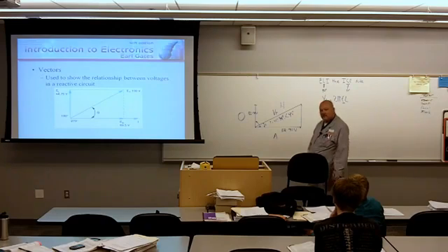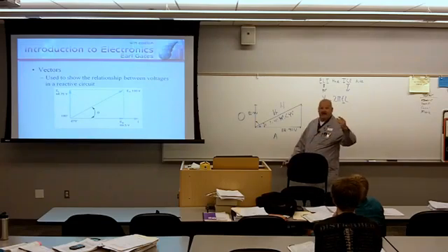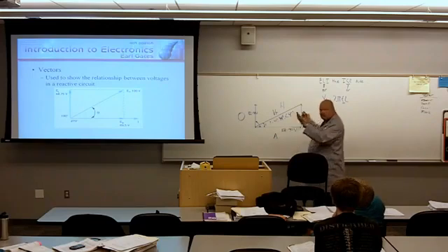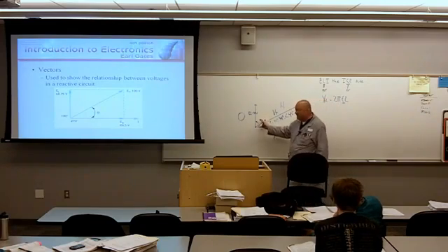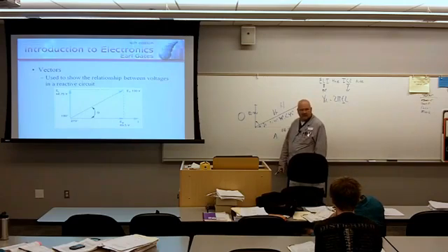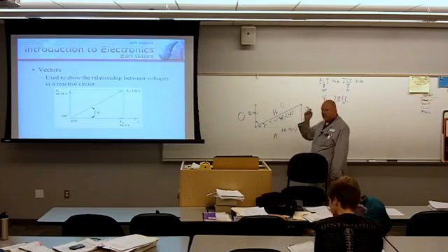Resistive circuit. But I do have some reactive elements to it. But it is more resistive than it is reactive. Why? I'm looking at it. I got 90 volts voltage drop across my resistor. I got 45 volts across my inductor. I got half of this. Half my voltage is across the inductor.